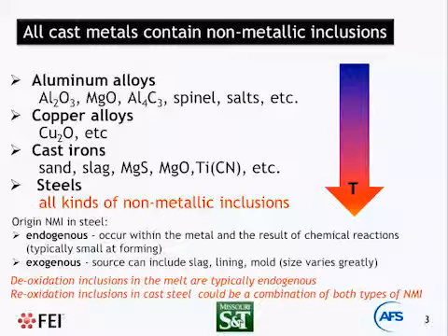It's interesting to mention that in cast iron practices, we consider that some inclusions can be very helpful because they promote graphite nucleation at lower melt superheat. This blocks cementite formation and the so-called chill zone, which decreases machinability.